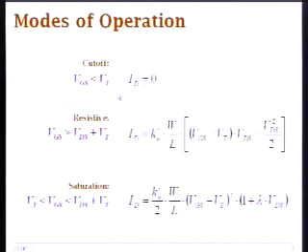So this is a summary of modes of operation that we introduced. For VGS less than VT, we assume that the current is equal to 0, but we will get back to that in more detail when we analyze power consumption and sources of power consumption, because that's not entirely true, since transistors are really conductive in the sub-threshold regime. There is leakage current, and we'll talk about that in more detail. But for the introduction here, we are mostly interested in the resistive and saturation modes of operation. So that's what you really need to understand here to be able to analyze delay and performance of circuits.